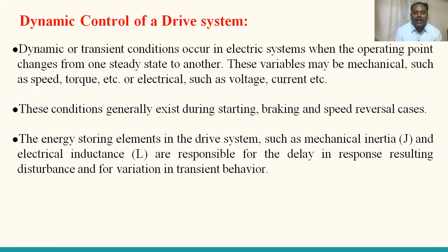What are the causes for these dynamics or transients in the electrical drive system? Particularly the energy storing elements in the drive system, such as the mechanical inertia J, that is the mass, and the electrical inductance L. These are responsible for the delay in response, resulting in disturbances and variation in the transient behavior.